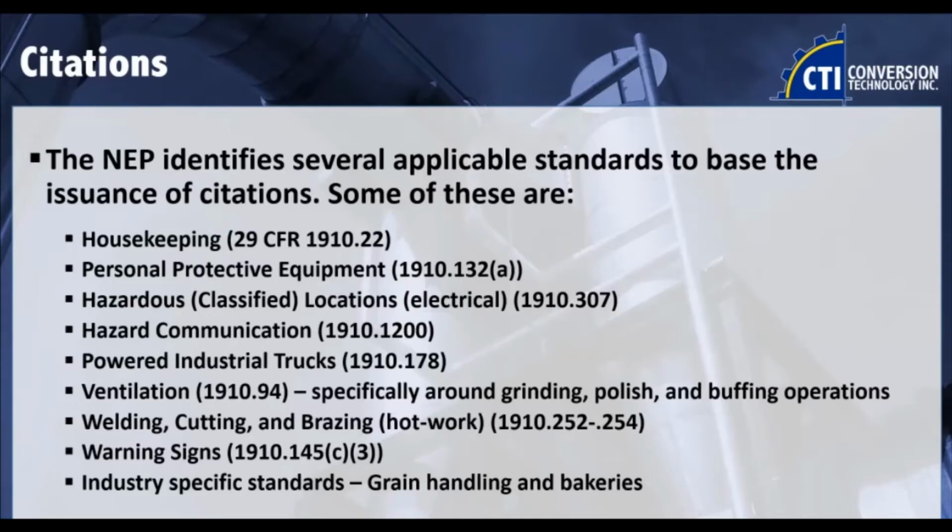As I mentioned, the standard specifies housekeeping. I look at housekeeping from a hazard standpoint, as there's plenty. If you don't clean the dust off a motor, that motor can become insulated, overheat, and now you have a fire hazard. So things like that. They'll look at housekeeping frequencies, what's used, how is housekeeping done, which I'll go over some examples more.